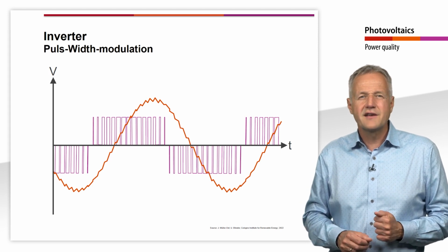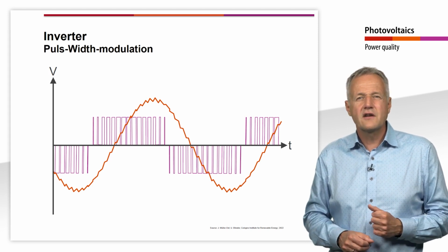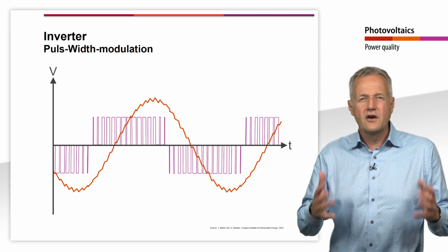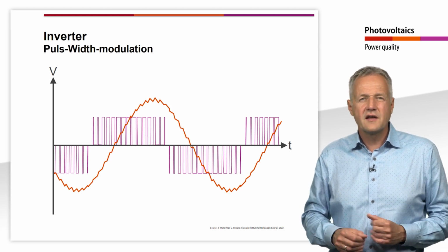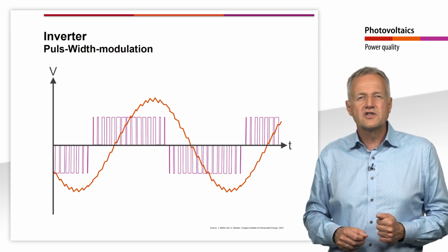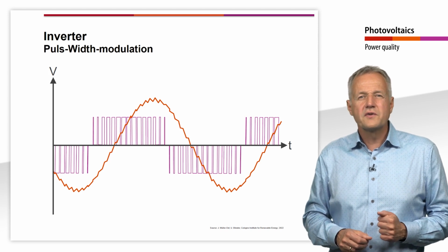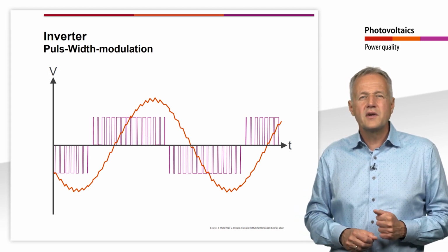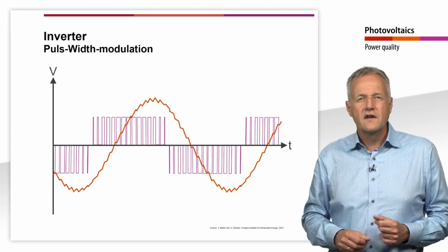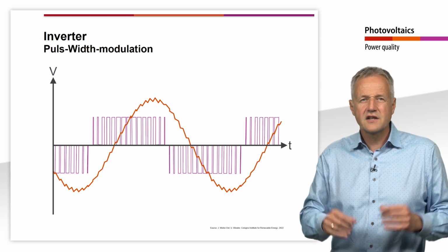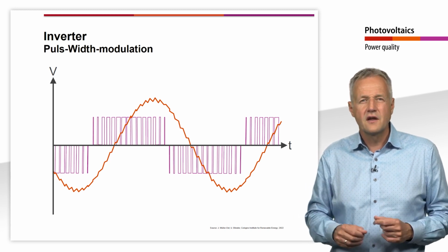However, it can be clearly seen that the output signal is now overlaid by high frequency harmonics. In order to limit the input of these harmonics into the grid, solar inverters are therefore equipped with additional filters that also reduce the high frequency harmonics. Most inverters meet the requirements of the standard with regard to harmonics and deliver a so-called certificate of conformity for this.